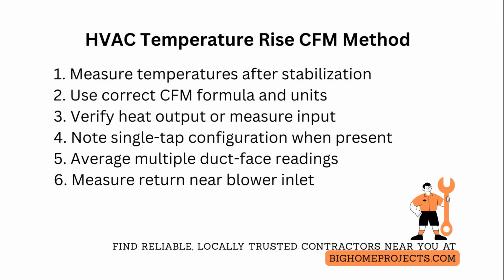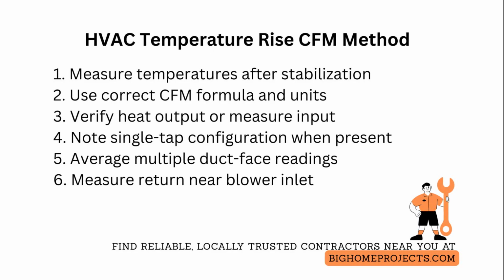Finally, record ambient conditions, equipment serial numbers, fan speed or drive frequency, and the exact method used so a later technician can reproduce or audit the measurement without guessing.